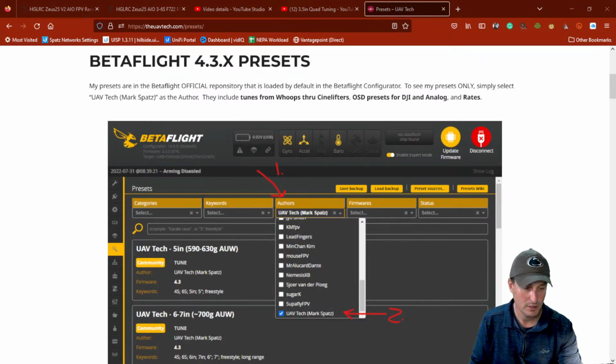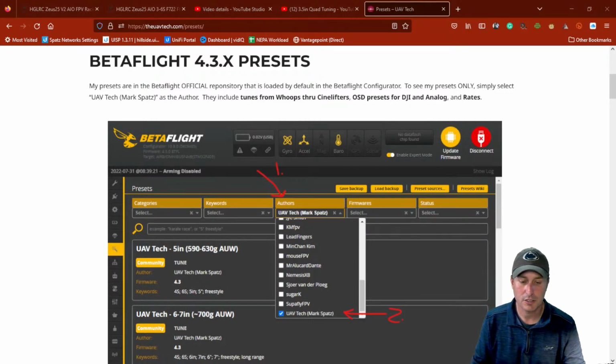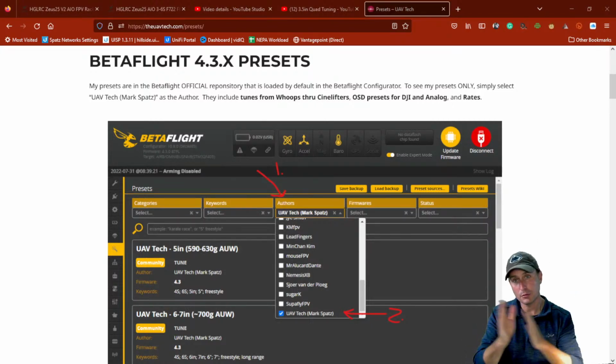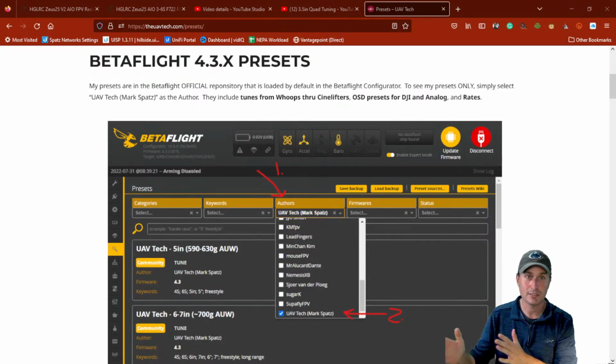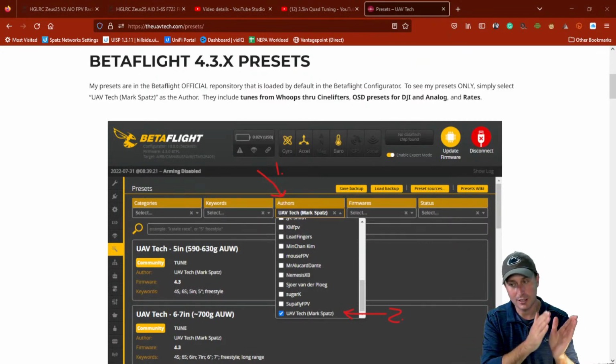The first thing I would do, if you can: 96 kilohertz is okay, but you're losing motor torque with that, like low end motor torque. So the first thing I would try, and I'm going to go through a bunch of stuff, but you don't do everything all at once. That's everybody's default reaction. Whenever I give advice, it's always do this one thing, then the next thing, then the next thing, because everything along the way is somewhat of a compromise, right?